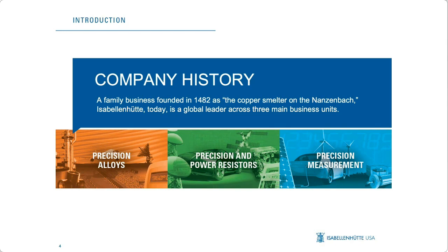And then we add different functionality like voltage sensing in some cases or isolation monitoring. And these modules typically communicate through a CAN interface and are fully temperature compensated over lifetime. That's why we call them smart modules.